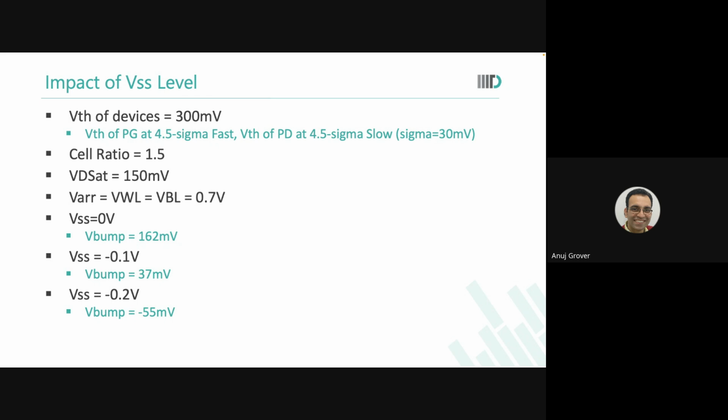Now, sir, do we have to generate a negative voltage? See, look at it like this. In our circuits, everything is actually relative. If you do not want to generate a negative voltage, you operate, let us say, the VDD at 5 volts, but GND is at 4 volts. What is the effective VDD the memory cell is operating at? 1. Now, instead of 4, you go to 3.8. So for that particular memory, it is a minus 0.2 level.